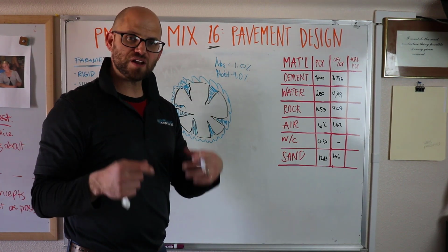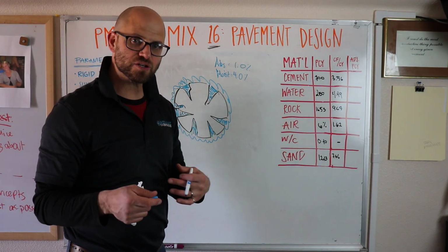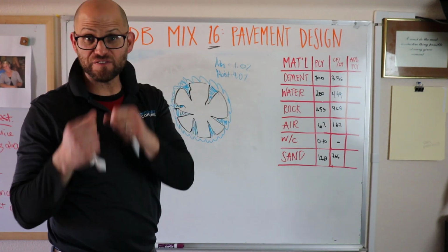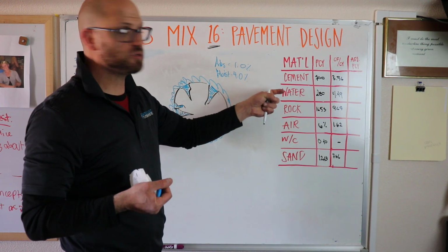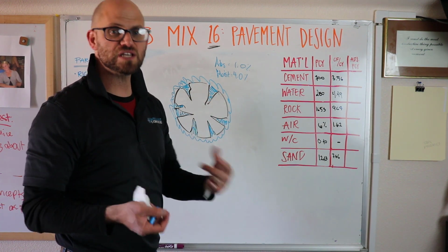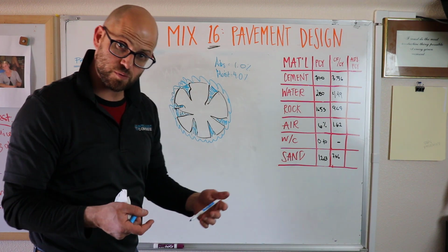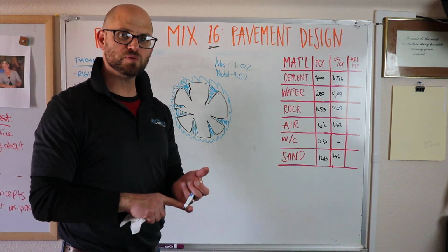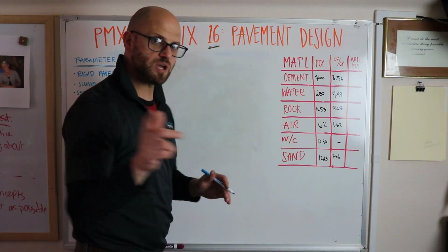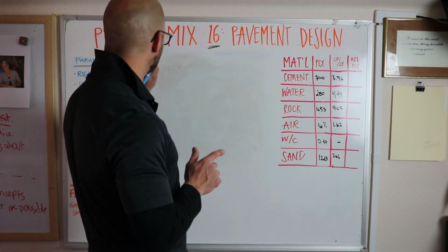So we'll have a certain amount of free water on our aggregate that we need to take into account, because that free water will contribute to our water cement ratio. And of course, if we don't take that into account, we put too much water into our mix. One, we might not make the fresh properties, but two, we might not make the strength and durability that we're going after. Okay, so the weight of sand. Let's start with the weight of rock.